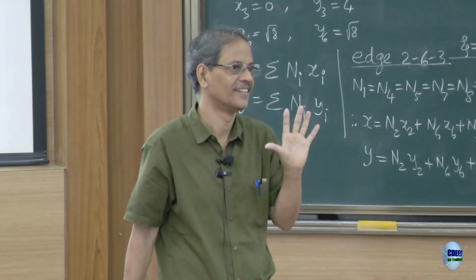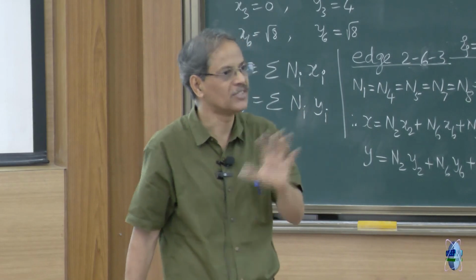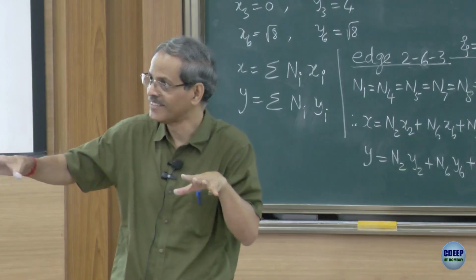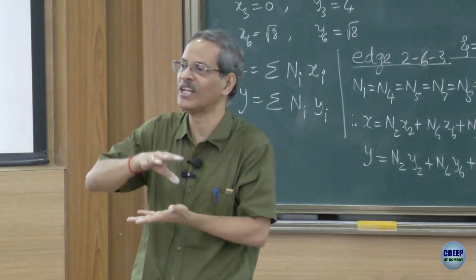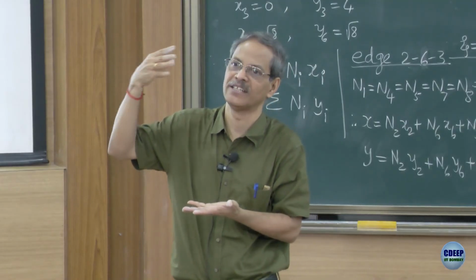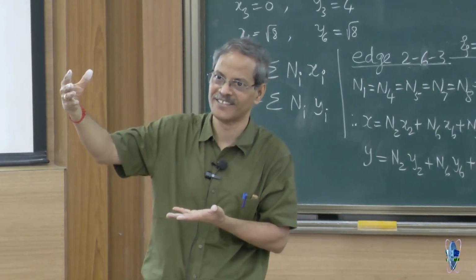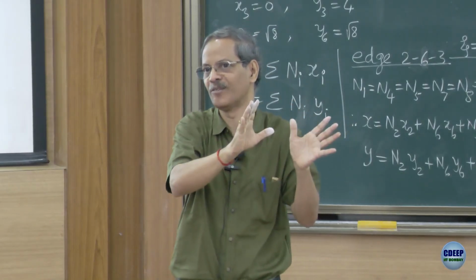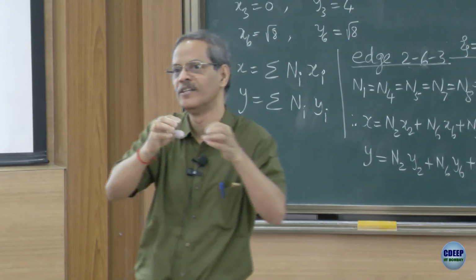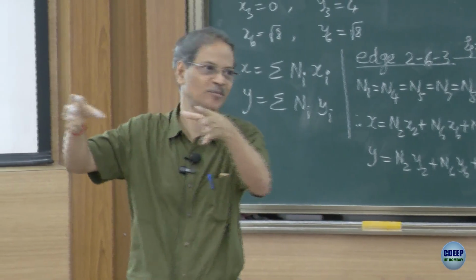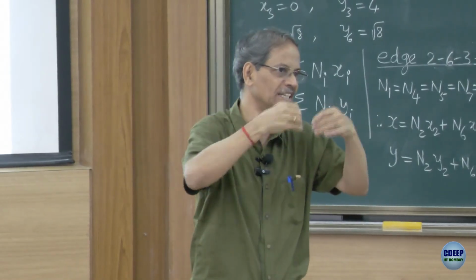Is that clear? We are trying to minimize it by taking H refinement or P refinement, which helps us not only in modeling the unknown field variables variation accurately, like whatever happened with the one-dimensional problems, where we took 2 elements, 4 elements, 8 elements, 16 elements, 32 elements, the solution improved even with linear.